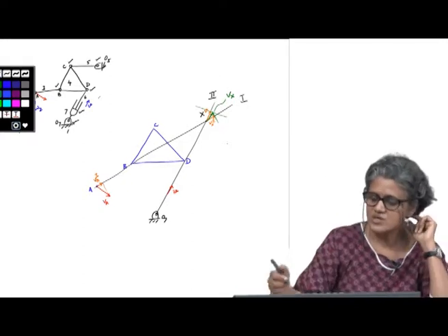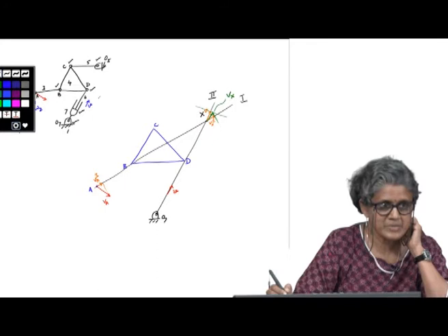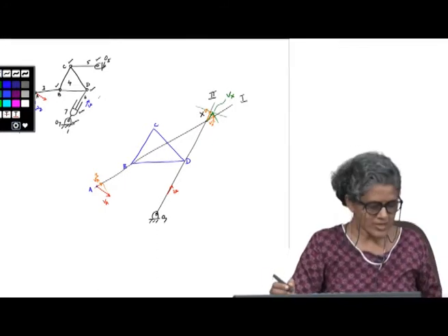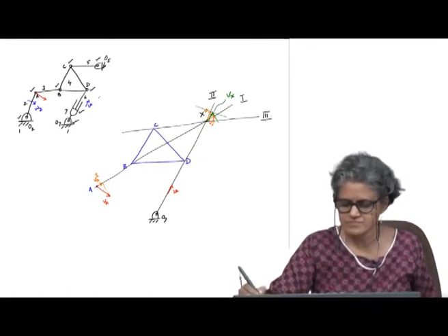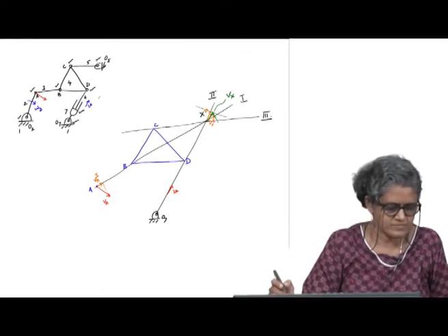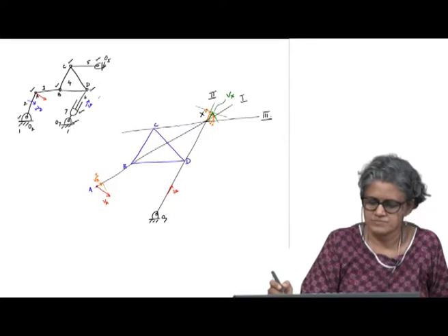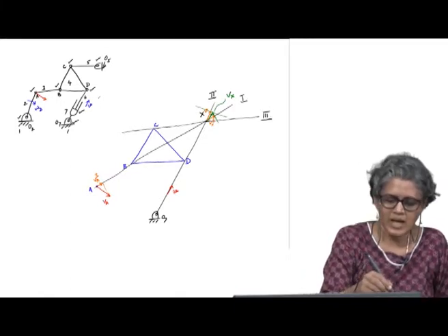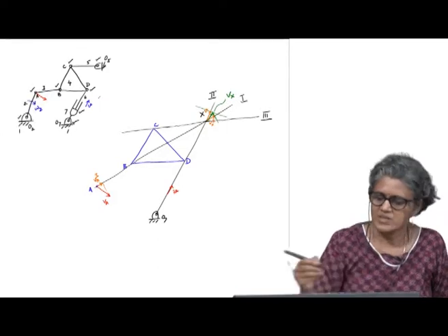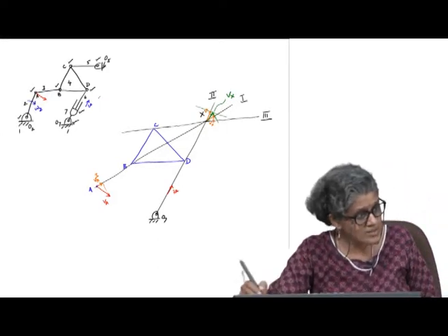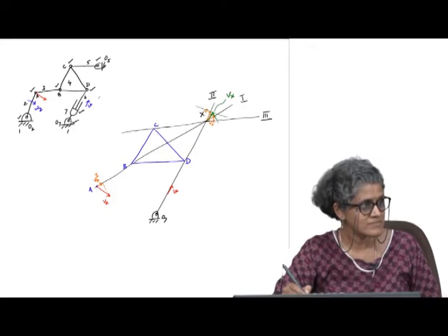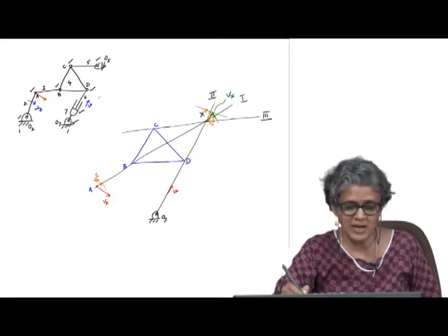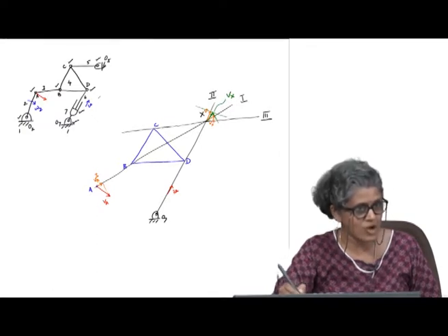Now, because I have the velocity of X completely determined, I can draw the third auxiliary line through C and X. Now, I can find the velocity of X along the line 3, and that is going to be the same as what is transmitted through C along that line.